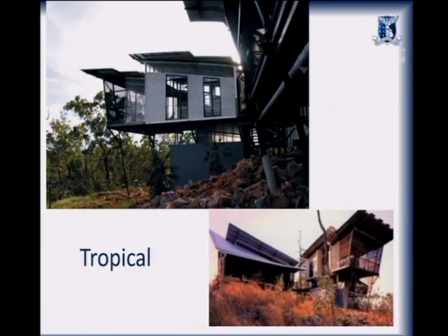So the emphasis being on airflow, you tend not to have thermal mass in this kind of environment because you're just keeping heat that you don't really want. You're also acknowledging that it's hot all the time. So you're not likely to shut down the building and try and have a different internal condition to outside. You're more likely to say it's really hot all the time. I don't want complete openings because of the mosquitoes, but I want air flowing around as much as possible. I don't want any connection to the ground, or as little as possible. So you have this really light design that allows air.